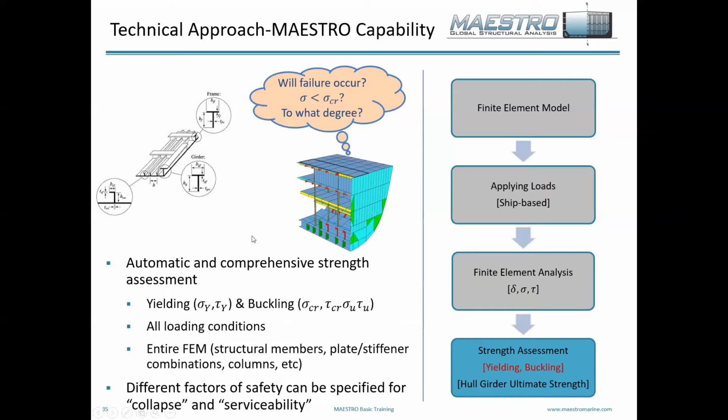And when you go to review in the post-processing options, you can evaluate just a single load case that was run, or present the results for a single load case, or you can say, I want to see the worst of all of them. And it'll basically show you a composite across the entire vessel for the worst case, or each element will present, I guess, the worst case of all available loading conditions.